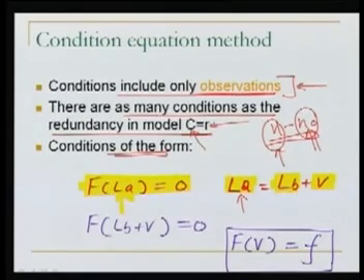LB is actually something which is observed in the field. We know this has some error. So what we are saying, error means the correction. In something which we observed in the field, we are applying this correction, and by applying this correction we get LA, that means the estimate or adjusted observation.